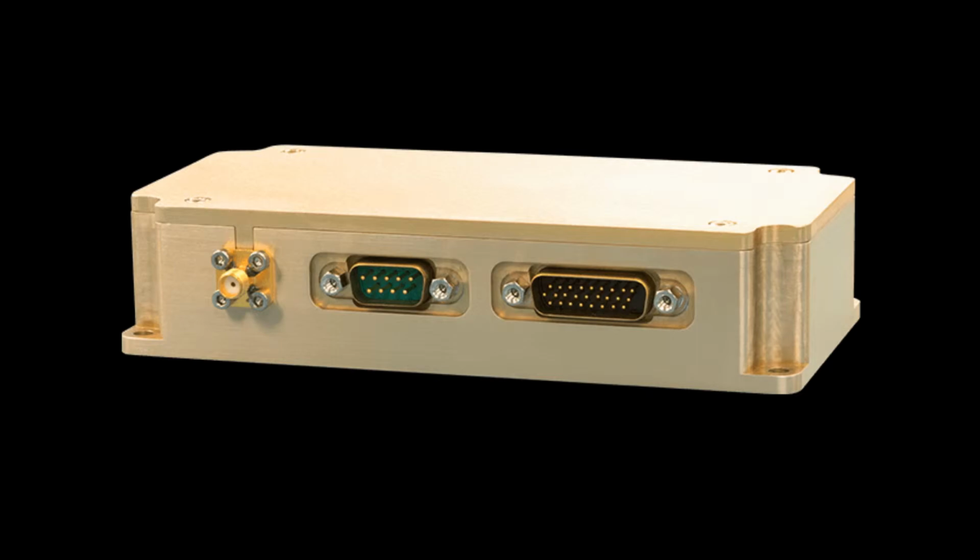These GPS applications have accurate determination of orbital position, the knowledge of time, orbit maneuvers and time, and position stamping of payload data. This antenna's transmission speed is 1000 bytes per second, so to transmit the estimated 10 megabytes of data of each flyby, we'll need about 2 hours and 20 minutes. According to the GMAT contact locator function, each of our contact periods while orbiting the Moon will be around 400 seconds, so each transmission will be done easily after each flyby.